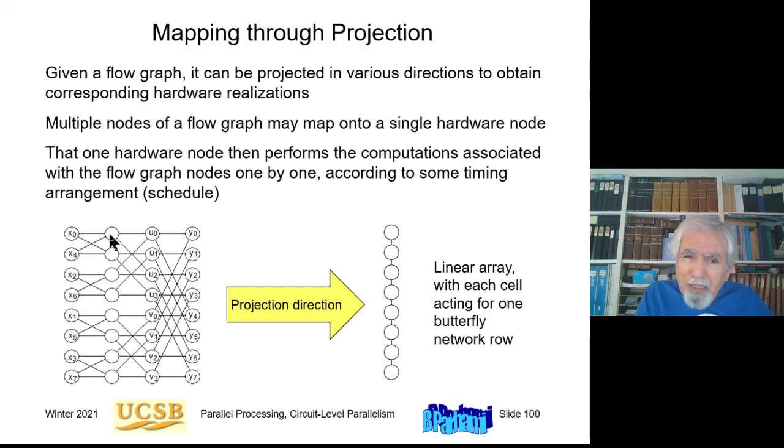But beginning with this column, you have the butterfly processors. So you have 3 columns of butterfly processors, or more generally log 2 n. So if these are 1024 points, you will have 10 columns of butterfly processors. So 1000 times 10, 10,000 circuit elements.